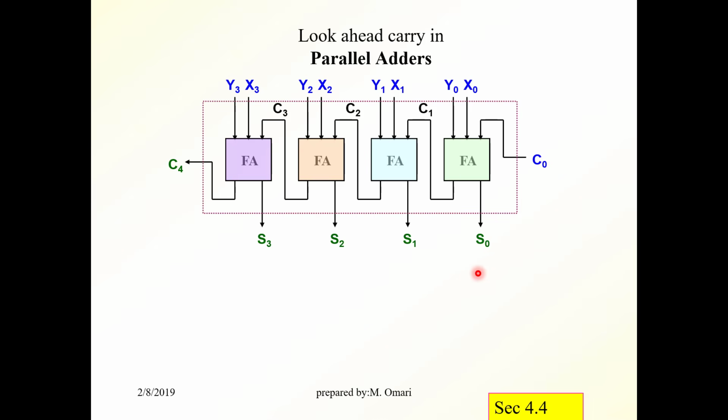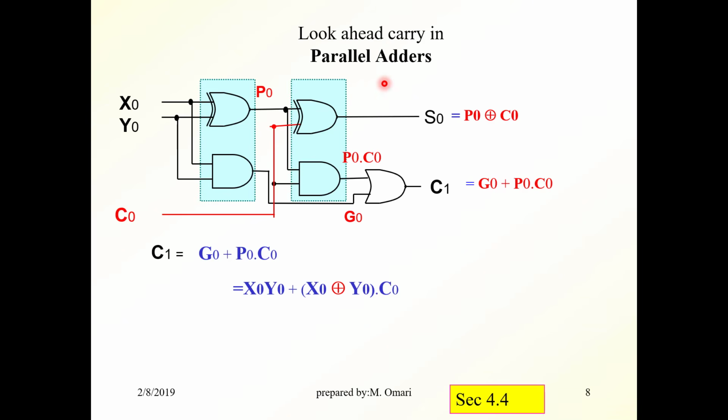Now, can we overcome this problem? Yes, if we redesign the parallel adder using a technique called look-ahead carry. Look-ahead carry means anticipating the carry before you have to wait for it to appear on the output. Anticipate its value. Okay, let's look at the full adder.